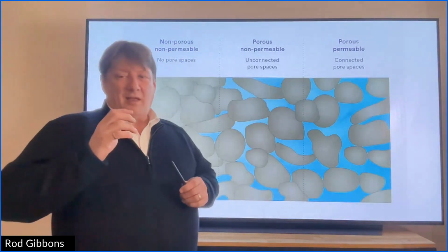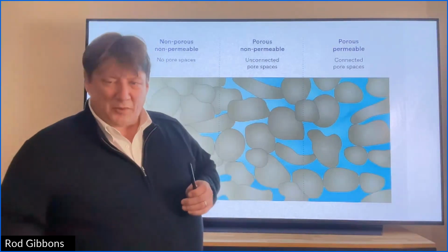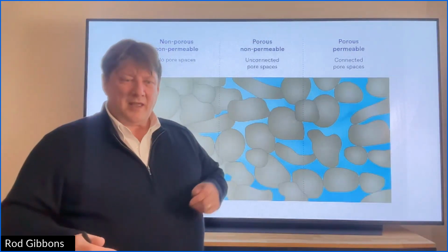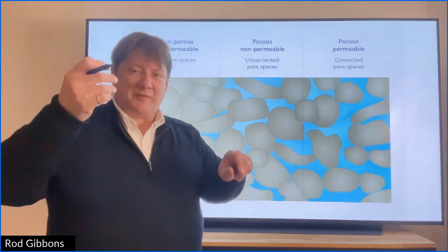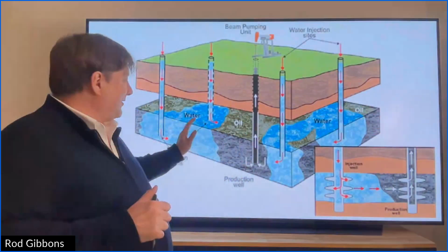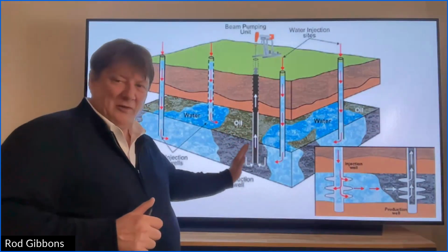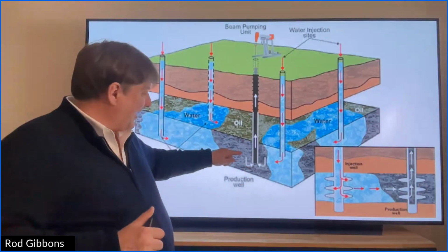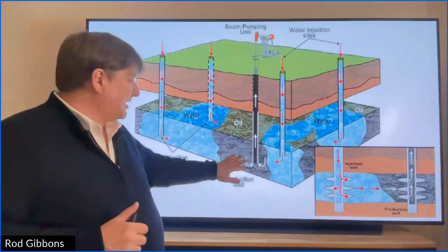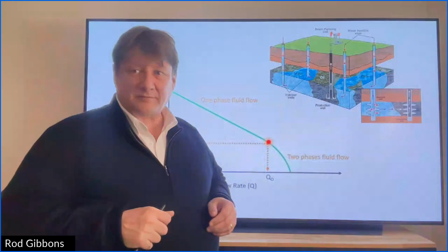A lot of times, a telltale sign of that is when you open the valve, the pressure drops very quickly, and when you close the valve, the pressure comes up very quickly. It's not coming from way back in the reservoir building up. It's very close to the wellbore. The pressure's still really high here. It's got to get across this damage. It builds up really fast. So that gives you a sign that you might have formation damage.